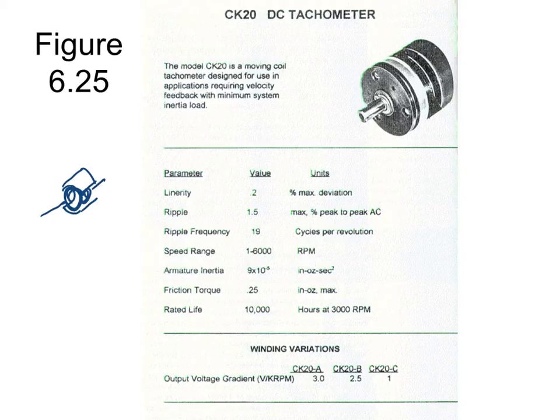Move through the magnetic field. So we've got wires, we got a magnetic field, and we have what? Motion. So these would induce a voltage into the little coils. The problem is by default, the voltage that these guys put out is going to be AC.